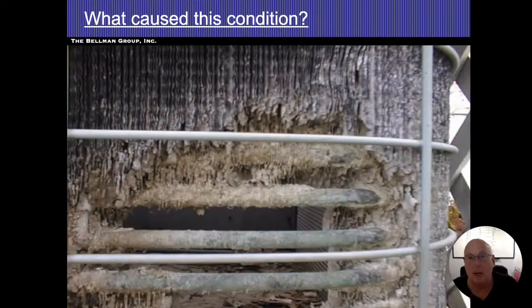All right. So just a couple pictures and a few things that we end up seeing here. I like this picture because it shows the tubes that the refrigerant is actually running through, and it also has the fins on there that the air flows through. Now this happens when a dog urinates on the air conditioning system. Those fins are very thin and fragile. A dog's urine is sometimes pretty acidic, so if they keep peeing on the air conditioner all the time, it wears away at the fins.